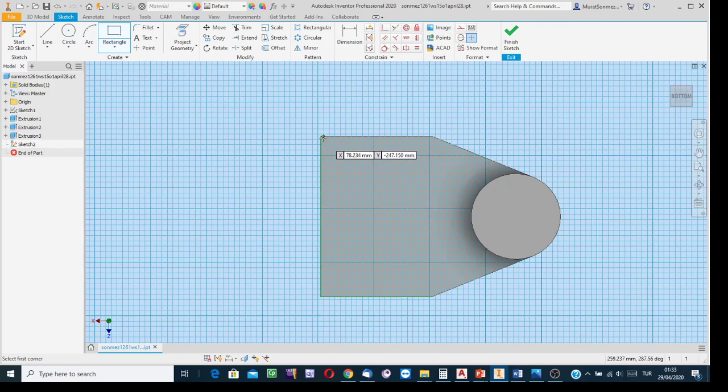You see when I bring the cursor to the vicinity of the terminal point of that projected boundary, it is just at the corner of the space. You see, I start seeing a green dot. The green dot is the highlighting symbol to say that the cursor is sufficiently close to that characteristic point, and if the mouse is left clicked, it can snap the cursor. In other words, this means you indicated the point. Indicate this point as the corner of the rectangle and then create the rectangle.